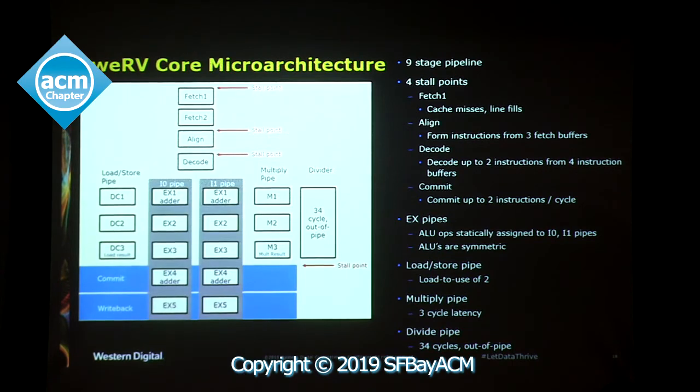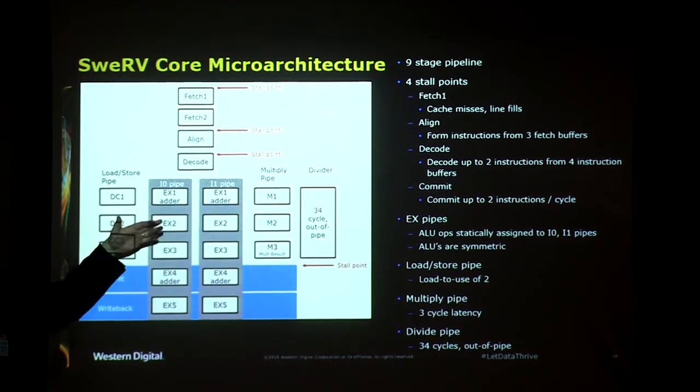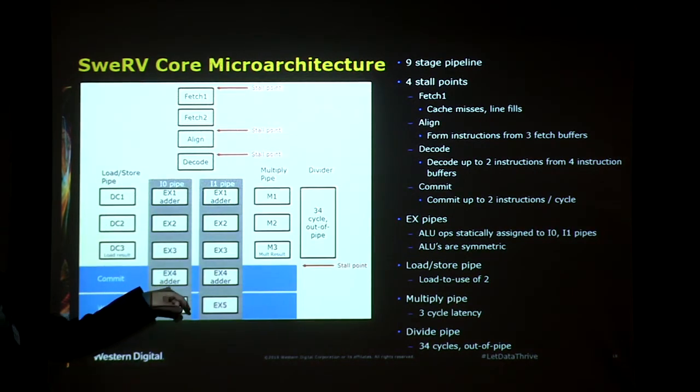More commonly, you have something that's called load to use in most computer architecture books, meaning you're loading from memory into a register, and then you're doing something useful. Now you're adding 16 to something that you loaded from the memory. And if that's the case, that load takes some finite time, and you miss this opportunity. In a classical pipeline, you'll have to stall until you get the data, and then you continue. Well, in this design, you actually continue, you don't stall the pipeline, and as long as your load is done in 2 clock cycles, you'll be ready, you'll get your second chance.